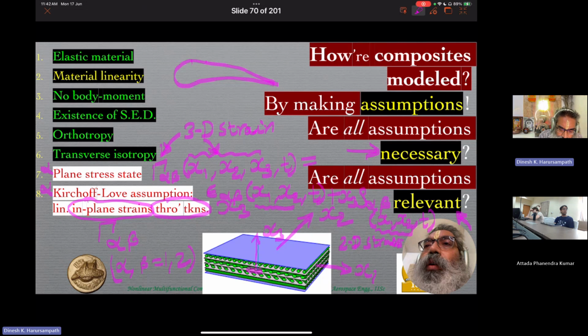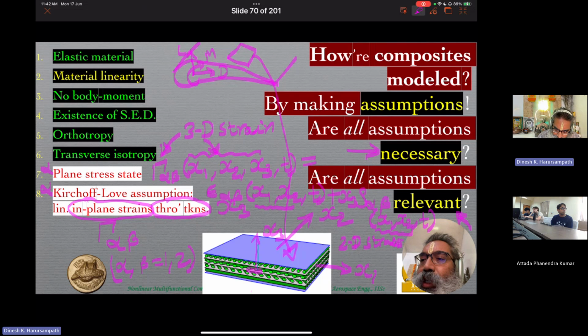So what we are dealing with over here is, let's say, a wing. The panel that we are talking about is a skin panel on the top, which is what we have drawn over here, right? Whereas the aerodynamicist might be giving you the loads at quarter chord, for example, for subsonic aircraft, where they might define the lift, the drag, the pitching moment, etc. So we know it at some other location which is much below here. So you could have, for example, x3 equal to 0 starting from here, where there is not even any material as far as this particular panel is concerned. Doesn't matter. It's just a mathematical way of defining it.